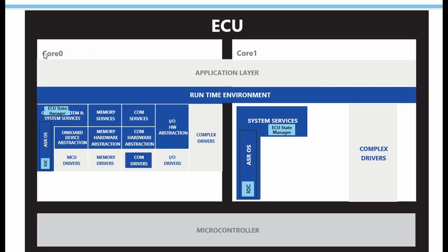See here you have core 0 and core 1, application RTE, and core 0 has the COM services, memory services, MCU drivers, memory drivers, IO, complex drivers and everything. And core 1 has complex drivers and some system services, that is ECU, AUTOSAR OS and everything.